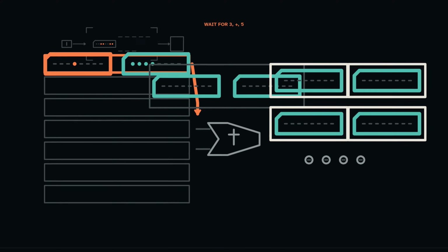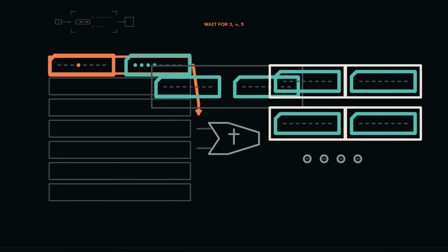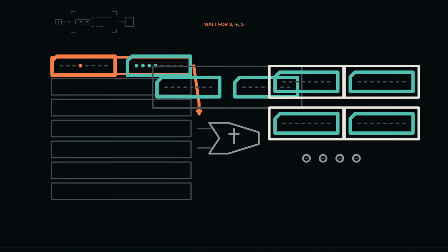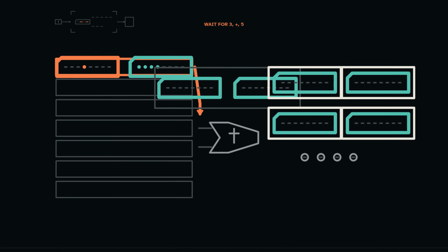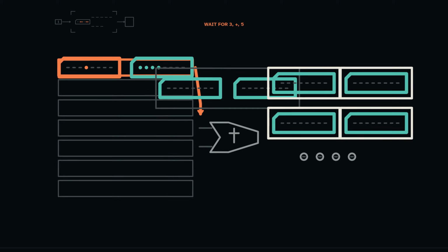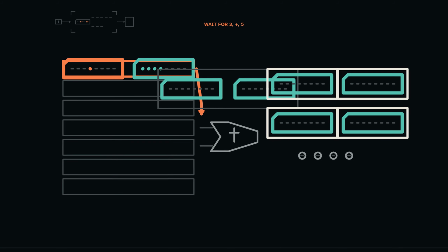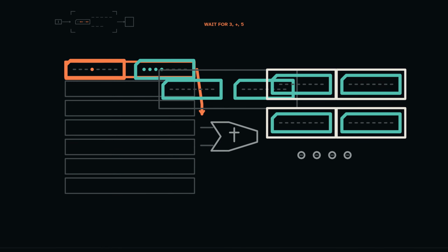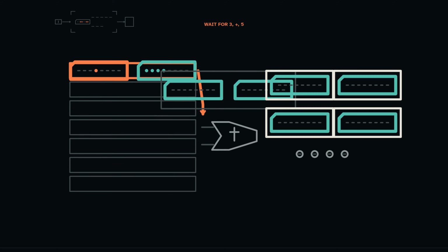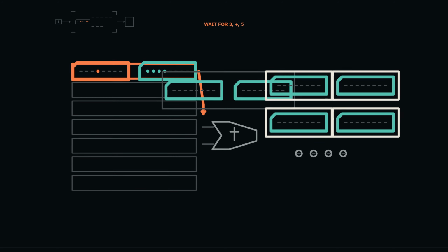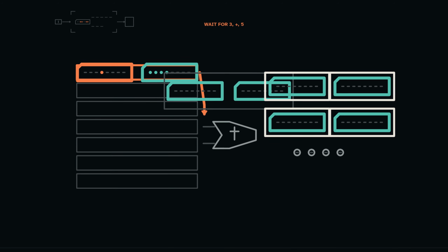This program waits for 3 separate input bytes produced by 3 separate key presses: 3, then plus, then 5. There is no joint signal carrying the whole expression. The first and third inputs supply the 2 operands. The middle input requests addition. The program converts both digit codes into quantities, verifies the plus code, computes 3 plus 5, converts numeric 8 back into a text code, sends it to the display adapter, and halts. Each input is scheduled only after the processor has entered its corresponding polling loop, so every wait and every arrival remains visible.